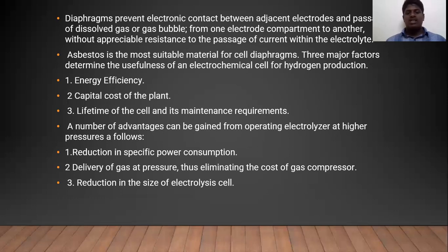A number of advantages can be gained from operating the electrolyzer at higher pressures as follows. Reduction in specific power consumption, delivery of gas at pressure, thus eliminating the cost of a gas compressor, and reduction in the size of the electrolysis cell.